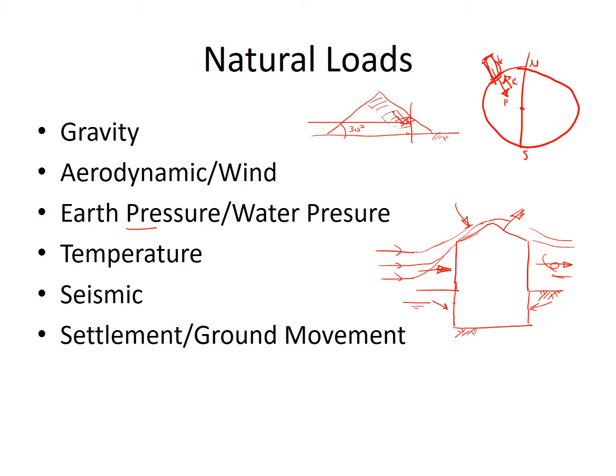So we will have to design this building for the water pressures, and those water pressures will be hydrostatic, so they will increase with depth. So we'll get a triangular load which can be resolved as a force acting in this direction, and we will also get typically an uplift on the basement floor, which is trying to push this floor upwards due to the water pressures again.